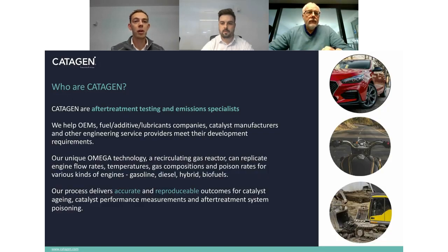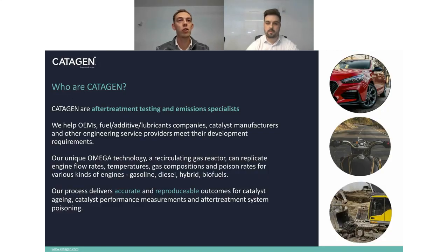So a little bit of background for anybody who hasn't had the opportunity to join us before. Who are Catagen? Catagen are after treatment testing and emissions specialists, and we help OEMs, fuel additive lubricant companies, catalyst manufacturers, and other engineering service providers meet their development requirements. And our unique Omega technology, a recirculating gas reactor, can replicate engine flow rates, temperatures, gas compositions, and poison rates for various kinds of engines, either gasoline, diesel, hybrid, or biofuels. And our process delivers accurate and reproducible outcomes for catalyst aging, catalyst performance measurement, and after treatment system poisoning.